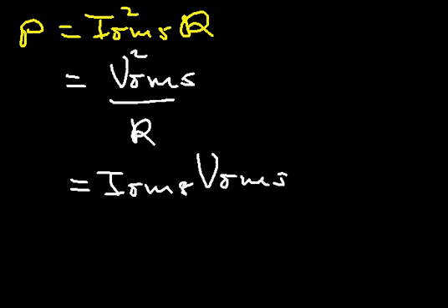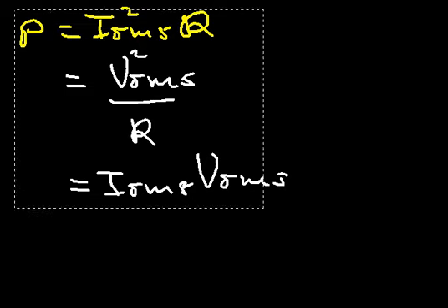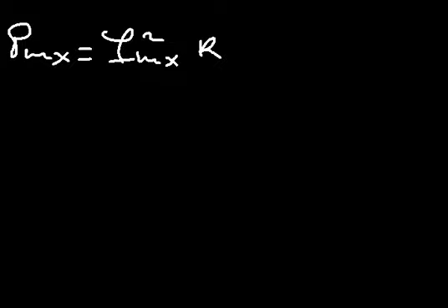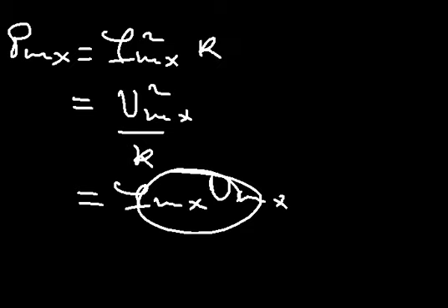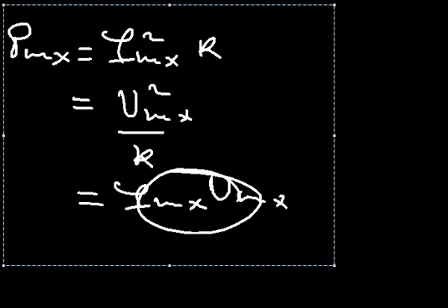And how about the maximum power? We can also have a maximum power. If that's the case, then we are going to use the maximum values. So maximum power will be given as Imax squared times the resistance. Also have it as Vmax squared divided by the resistance, and we can also have it as Imax times Vmax. You'll be able to have the maximum power using that formula. So take note of that.